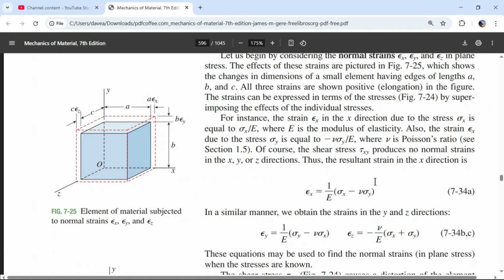So hell yeah, we just spent quite a bit of time talking about where this equation would come from. Now we see sigma divided by E, because if I got this E to the other side, to really simplify the equation that relates stress and strain, you have sigma is equal to modulus of elasticity times strain. So sigma is equal to E epsilon, but you could call this E, who cares? It's the Greek letter epsilon, I would imagine. If it's not, shame on me.